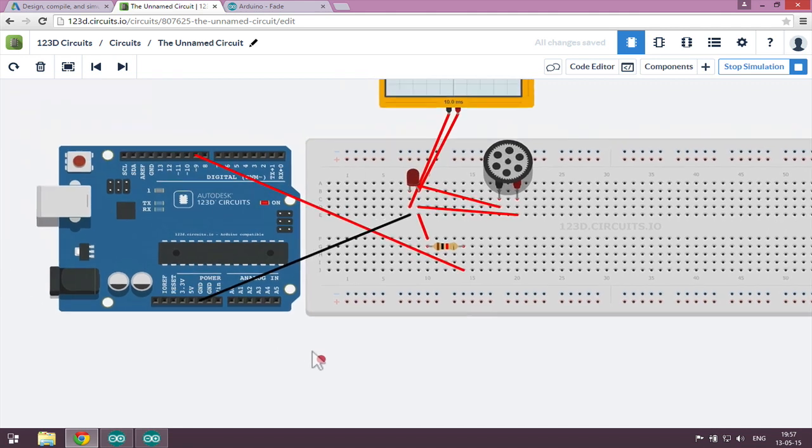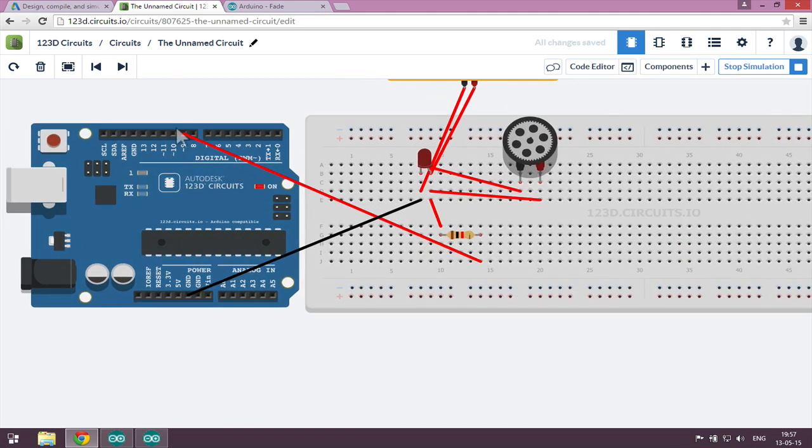You're going to use this inside your projects a lot. So this is a godsend that we have pulse width modulation on these pins, because most DC motors have one operational voltage, and that's 5 volts, and that's full speed. So if you want to change that with an Arduino, you can use pulse width modulation to control the rotational speed.